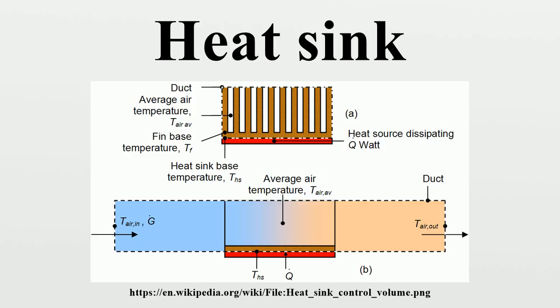In a vacuum or in outer space, there is no convective heat transfer. Thus, in these environments, radiation is the only factor governing heat flow between the heat sink and the environment. For a satellite in space, a 100 degrees Celsius surface facing the sun will absorb a lot of radiant heat, because the sun's surface temperature is nearly 6000 Kelvin, whereas the same surface facing deep space will radiate a lot of heat, since deep space has an effective temperature of only a few Kelvin.